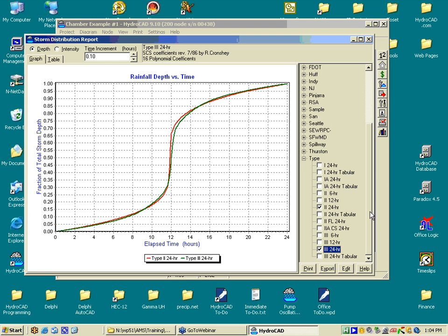So when we link over to HydroCAD through the HydroNet Explorer, that link basically focuses only on the cutting of the layers to produce the composite curve numbers for the watershed, and the DTM aspects that give length of flow, watershed average slopes, all the sort of DTM and layer-based input that's necessary.